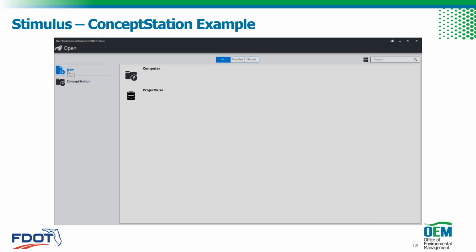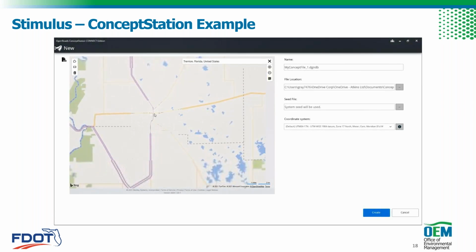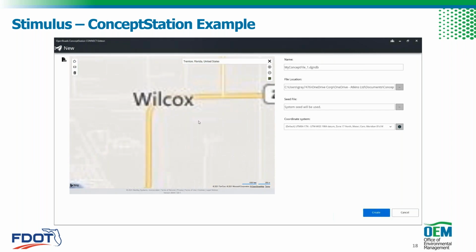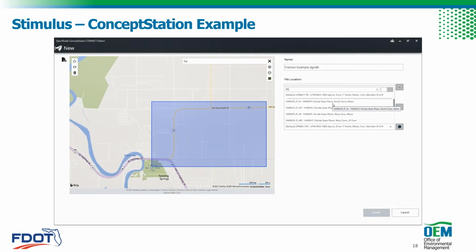So I'm going to start the video, and I'll pause it at some places along the way. So what I wanted to note, it simply starts with typing in a location, right? I chose this region, and then now I'm just going to select the area that I want to develop a model around. I give it a name and then select the appropriate coordinate system for that data.